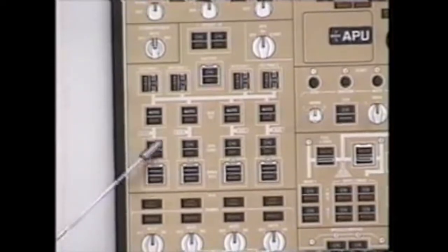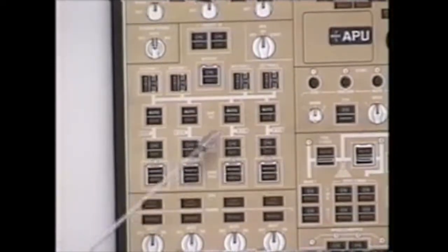Generator control switches. During the cockpit setup, your captain is going to turn the generator control switches on, but they will still stay off because the generators are not physically turning. It's impossible for the relay to close. IDG disconnects. If you disconnect an IDG, maintenance has to reconnect it on the ground with the engine shut down. There's an amber drive light in each IDG. The amber drive light illuminates for IDG high oil temperature or IDG low oil pressure.